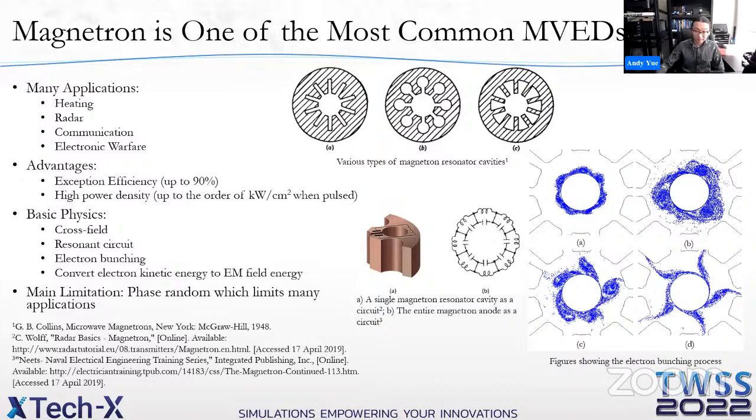Magnetron operation is a chaotic process. During the magnetron's operation, the cathode emits electrons, and the electrons form a hub around the cathode. The magnetron is a cross-field device, namely the applied DC electric field between the cathode and the anode is perpendicular to the applied magnetic field. This field configuration dictates electrons in the system following an E cross B drift motion described by the Lorentz equation.